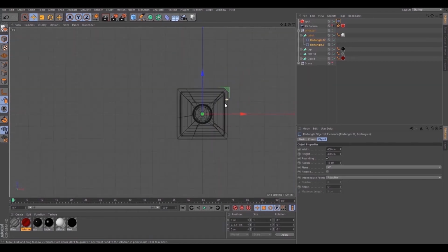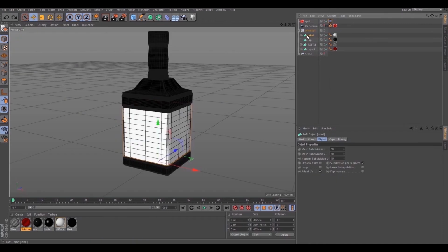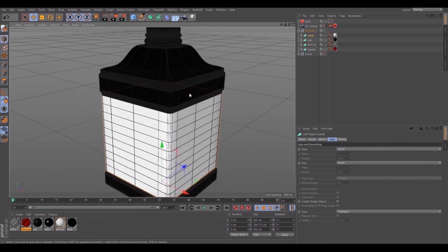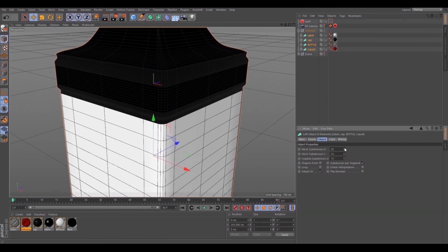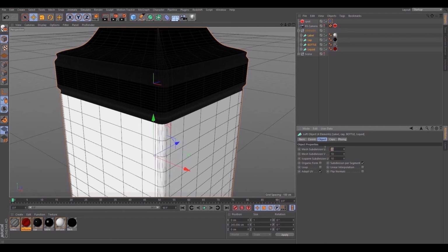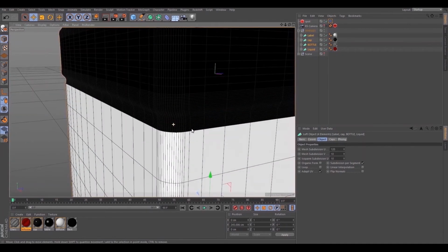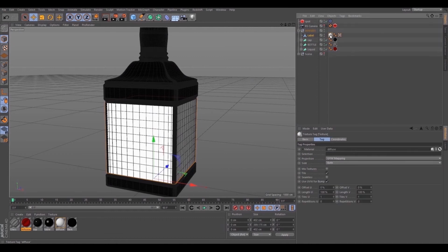In top view, scale up a little these rectangles. In loft settings, choose Caps tab and select None. Select all lofts and increase mesh subdivision maybe 120, so it looks smoother on angles. Now press C or this button to expand loft. Create new material for label.